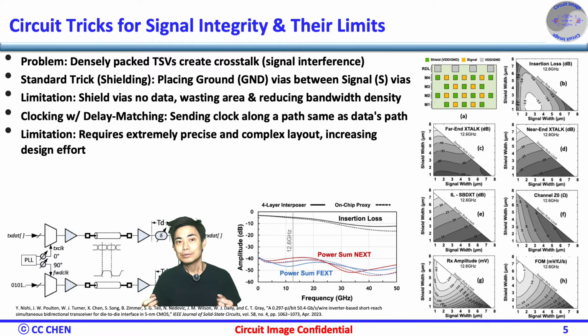More advanced receivers can cancel roughly 70% of crosstalk with kernel techniques and precise termination, but they add analog complexity and delay. Matched clock forwarding gives robust timing only if the clock path exactly matches the data path. Every trick has a trade-off.